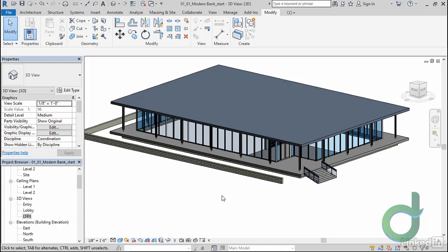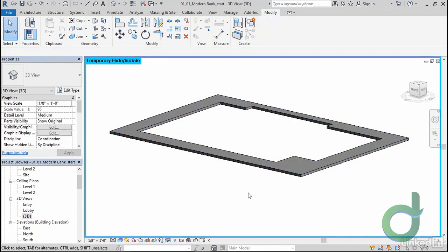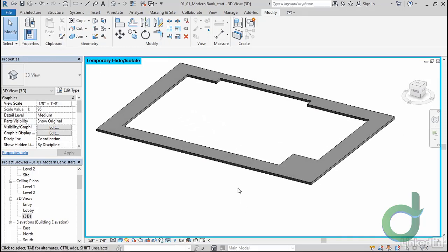Back here in Revit then, I'll take a look at some large meshes and identify possible problem areas. The first is the floor. I'll select it and isolate it to show what I've done. I've cut this floor slab out, a structural floor, cleanly around the curtain wall, or actually halfway under. And this way, I can cleanly isolate the outside, which is more likely to be in direct lighting from the sun, from the inside, which is more likely to have either dappled interior lighting from screens, plants, or interior lights, or muted lights through, again, screens where the sun shines through. Separating inside and outside floors then, even though they are the same structural slab, is important.